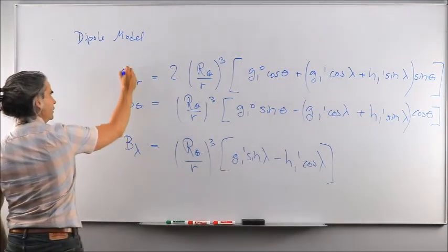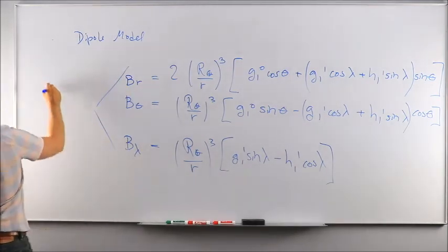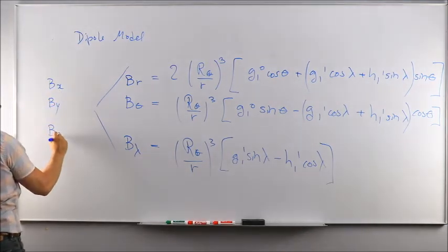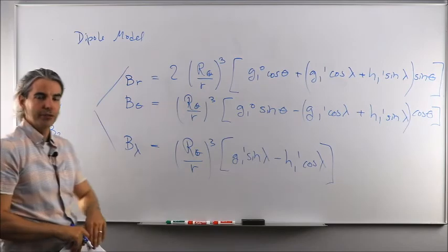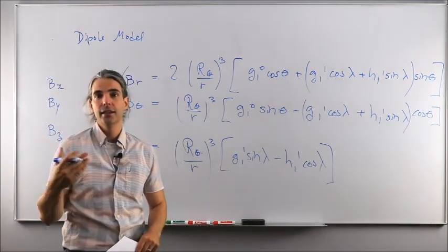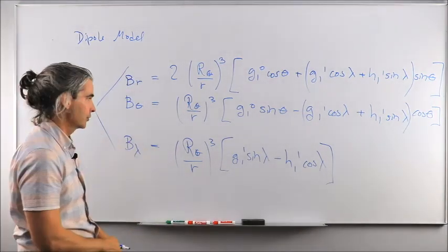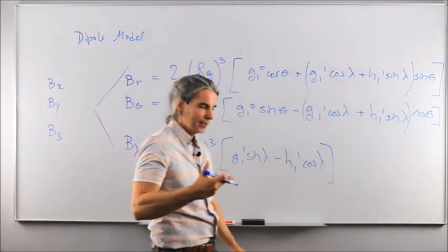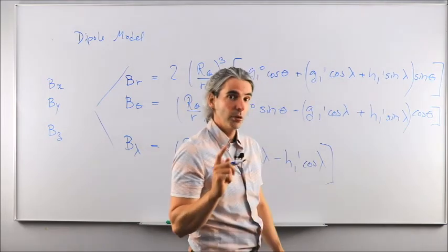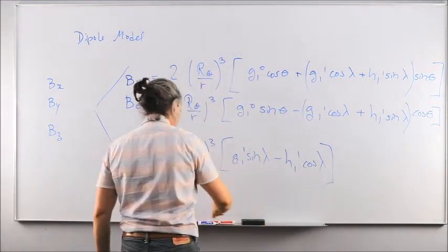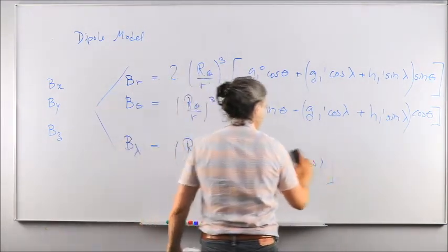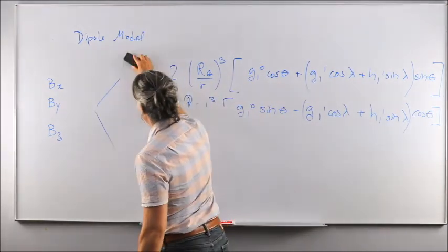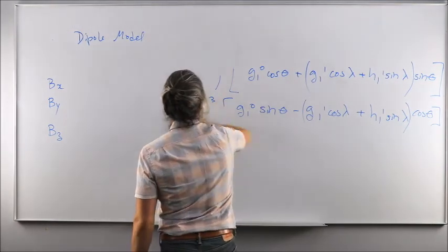and then obviously you turn that into Bx, By, Bz, or the XYZ components of the magnetic field of the Earth seen in the Earth-centered inertial reference frame. Okay, and now we've seen 3 different ways to obtain Bx, By, Bz. Now the only question that remains is how can we use that practically to calculate the magnetic torque affecting the spacecraft in the body fixed reference frame. Okay?